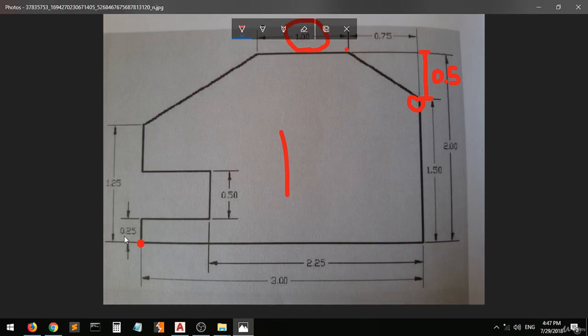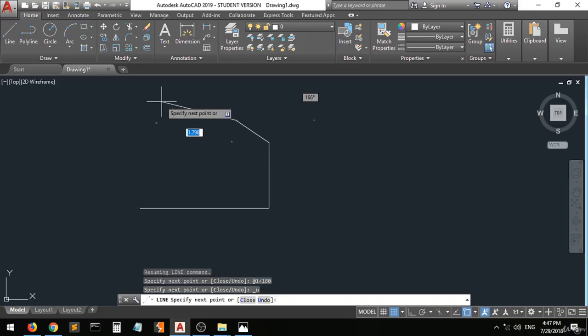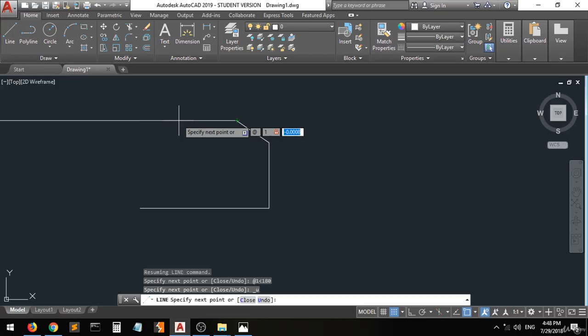Vertically with 0.25. But first of all, let's do this again in the coordinate entry, okay? So we have put this in the polar entry. Let's do Ctrl Z for the undo. Now let's use the coordinate entry, okay? You have to type what is the length or what is the x coordinate of this line. It will be 1 slash, in the y-axis we're not moving, so we will type 0 and now enter.